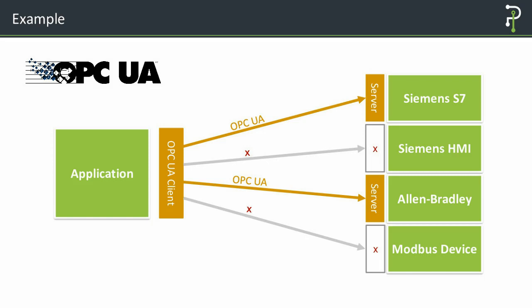So you can start to ask the PLC, okay, what kind of values do you have? What data types do you have? When were these values measured from the sensor and all that stuff? So OPC UA has the big advantage that it makes it way easier to see what kind of values you have, it makes it type safe, it gives you quality of service, and it gives you quality markers for specific signals. So there are really situations where it makes a lot of sense to work with OPC UA.